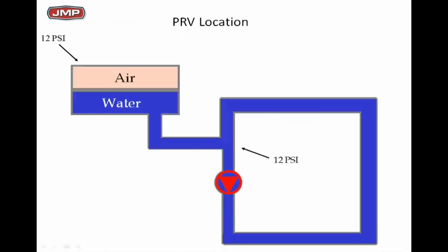Let's take it a little bit further with tall building examples and pressure reducing valve locations. This 4 pounds at the high point is desirable to have a slightly positive pressure with the pump off. And by doing that, we can get most of the air out. So this pressure reducing valve location becomes pretty important. What you really want to do is control the pressure at the point of no pressure change. You want to control the pressure of the expansion tank.